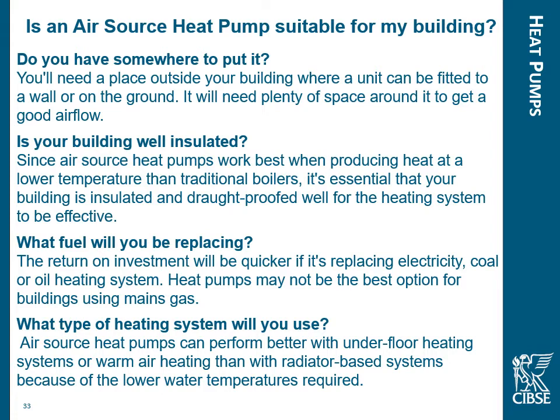Is your building well insulated? Well, since air source heat pumps work best at a lower temperature, as it were, we need to make sure we don't lose that low grade heat. So our building needs to be extremely well insulated, which works well on new builds, but they can struggle on existing builds because we sometimes struggle to get the insulation level high enough for them.